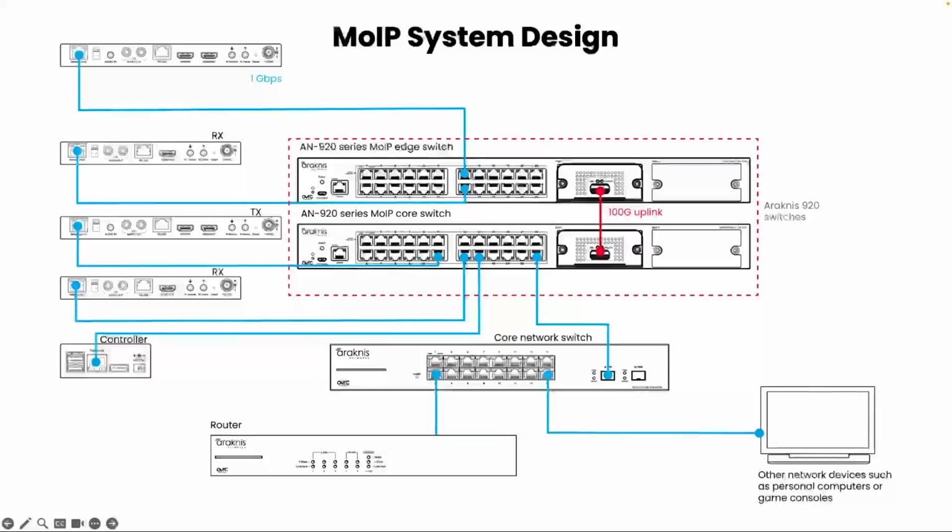Now, if you're building a bigger system where you have multiple 10 gig switches, some things to keep in mind: you're going to have to allocate 10 gig of bandwidth for each transmitter on the second switch. You're also going to have to allocate 20 gig of bandwidth for each receiver on the second switch with access to more than one source from the first switch. So transmitter bandwidth and receiver bandwidth must be greater than or equal to 100 gig. And then one transceiver equals 30 gigs.